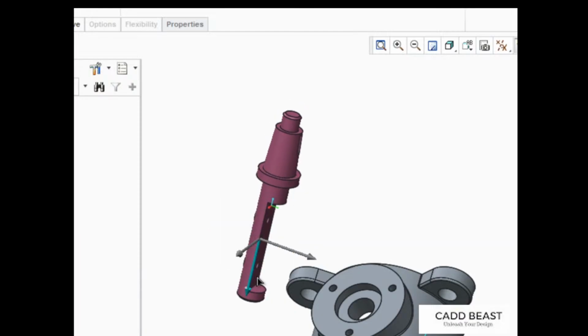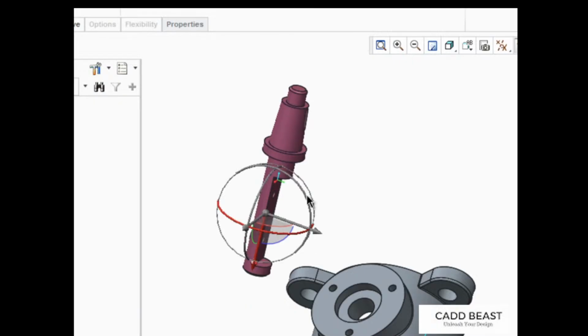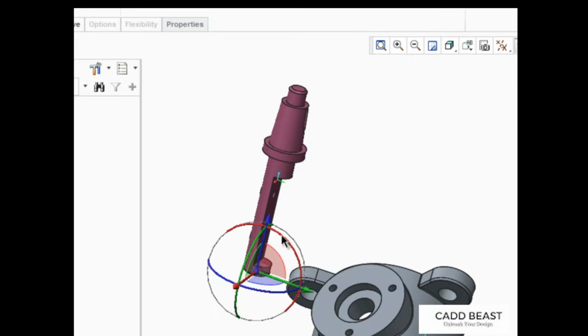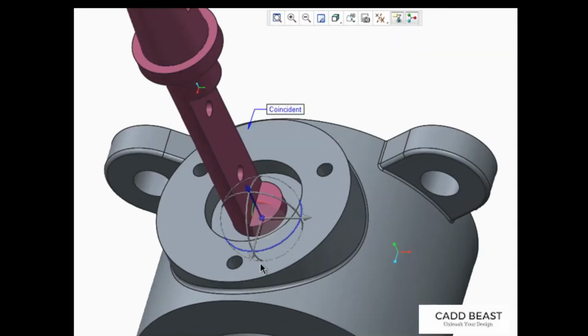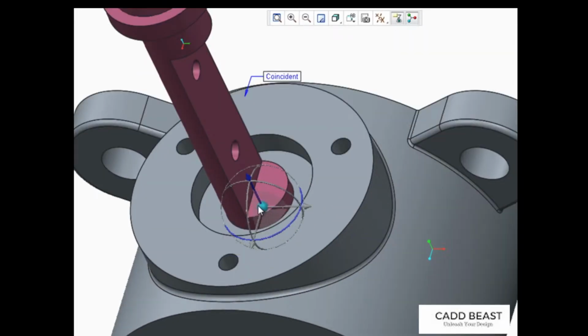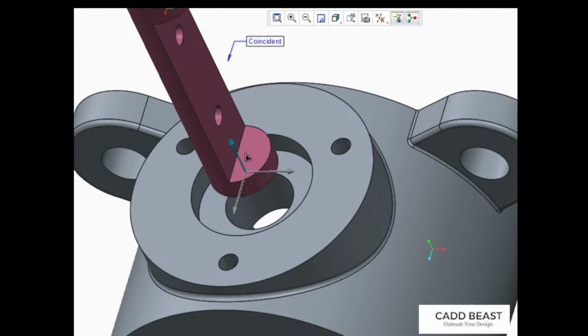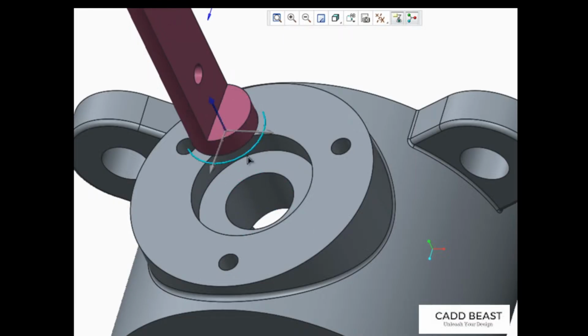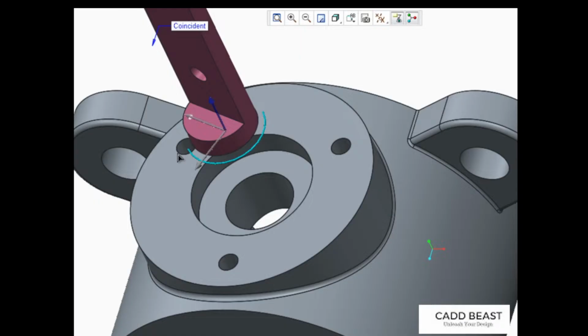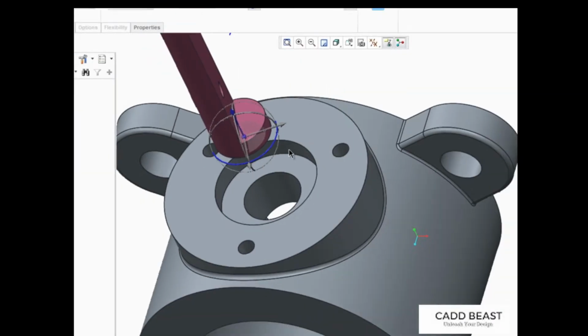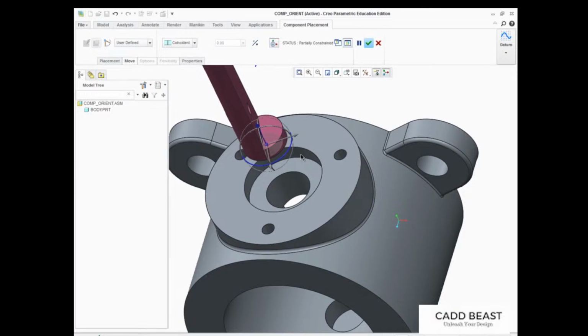The remaining degrees of freedom can't be used to manipulate the model while dragging along that edge, so they're grayed out. As additional degrees of freedom are reduced by adding more constraints to your assembly, you'll notice that those corresponding portions of the Dragger are also grayed out. An example is a shaft inserted in a hole, which limits motion to only one rotational axis and one translational axis, which are the shaft's remaining degrees of freedom. The new 3D Dragger provides you with an easier, more interactive method to move your components about in assembly, while respecting the limitations of the constraints you've specified.